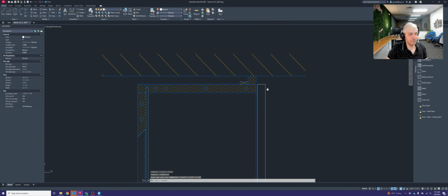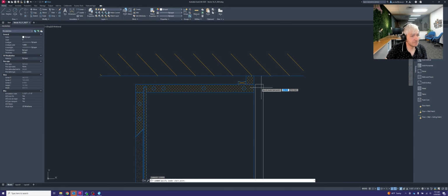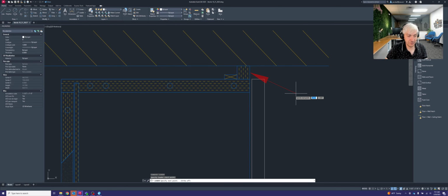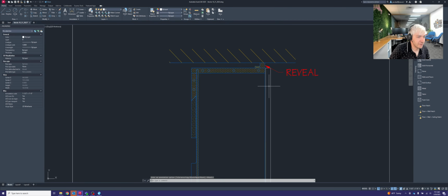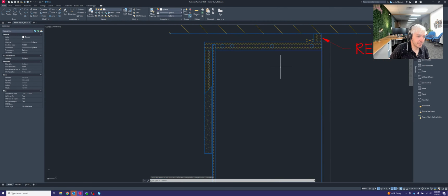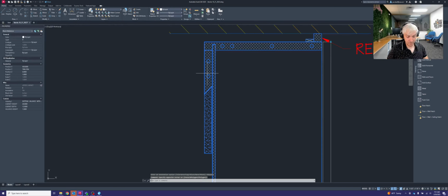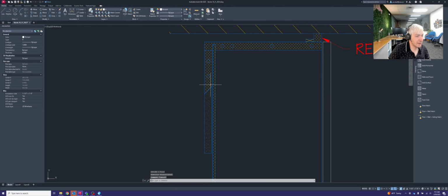And the reason that reveal exists might surprise you. You might think, well, maybe the soffit's wavy too, or the ceiling's wavy too, just like the drywall or the floor. Well, there may be a little bit of that, but really the reveal is there for the purpose of, as you're installing this cabinet, the cabinet and the cleat that are attached to the cabinet need to have what's called lift-off space.